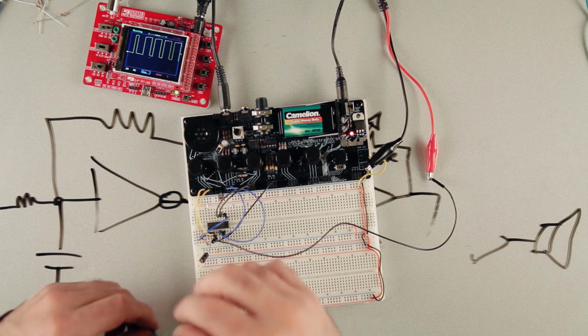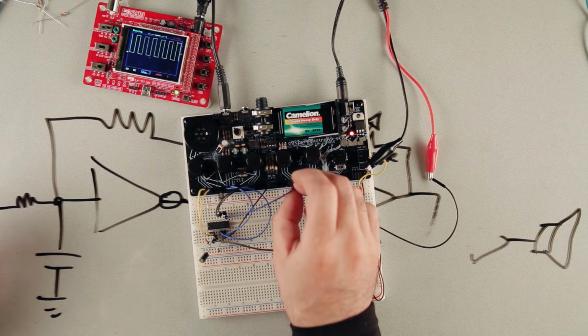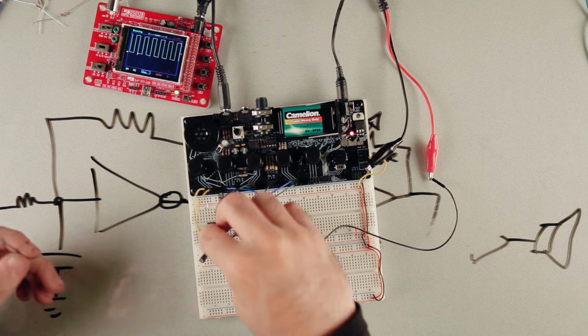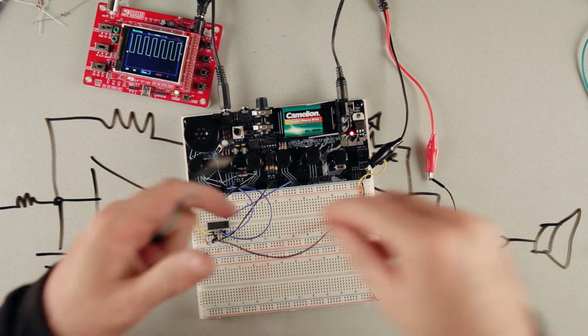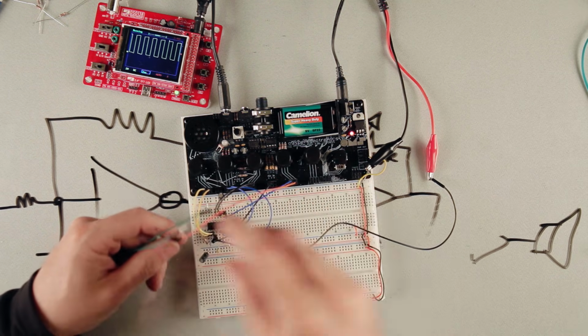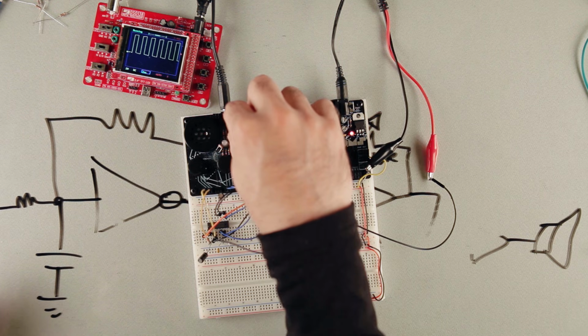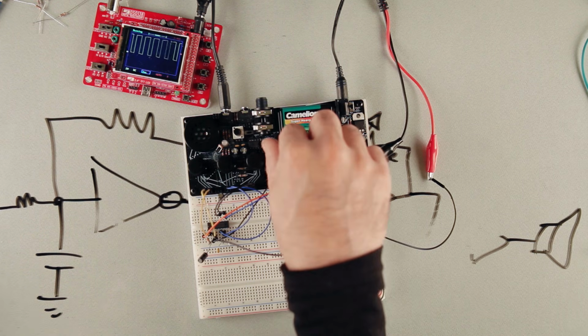And now what I can do is I'm going to take that, and so that I can make it a variable LFO, I'm going to plug it through a potentiometer. So instead of just going straight in, my wire is a little too short. Let's get another wire. So now I'm going through this potentiometer and then to the input. And so there it's relatively soft.